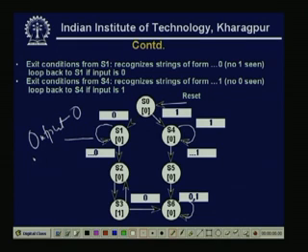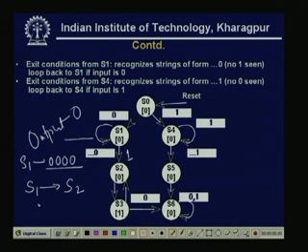So S1 recognizes 0 0 0, this type of input string. Now only one shift will be there when a 1 comes. So now a transition will occur from S1 to S2. But the string identified is 0 1. So again output is 0. So here output is 0.